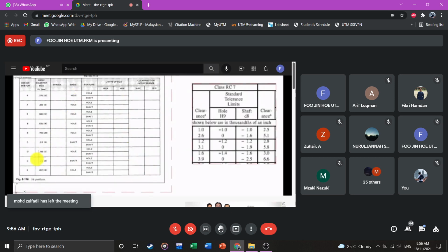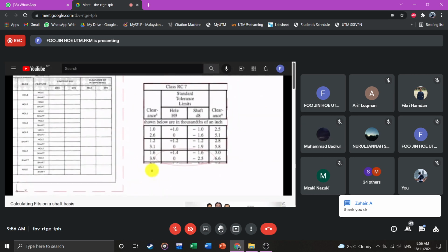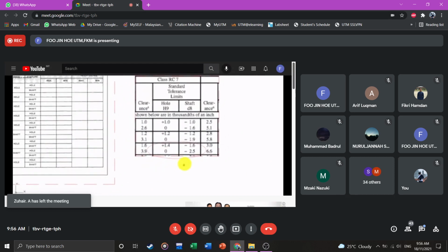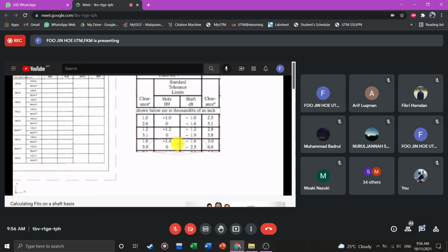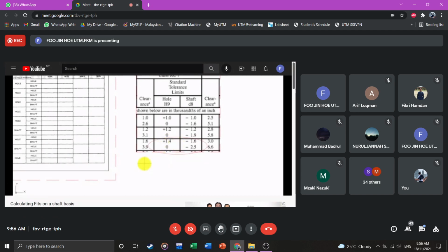Now we come over here to D, 312. So we're still dealing with 312 thou. So what I've done here, the one that refers to the category or to the range that includes 0.312 or 312 thou. So I'm going to do the same thing. I'm going to start by calculating on a hole basis, and it's easy. We just start by using max material condition size of the hole. It's going to be the nominal size. So we'll do the same thing we did over here.